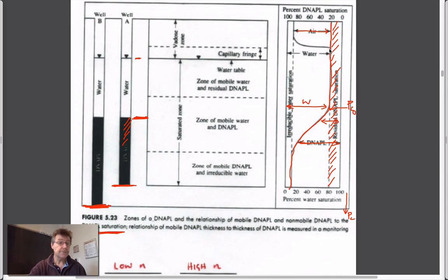And so in this case we don't have to worry as we did before, but I guess the other thing which is important to notice, say the capillary barrier was here, and you drill a hole down to here. Well, of course it will fill up to here based on what falls out of the aquifer. If you now over-drill this hole, so now it's deeper, and it still has a capillary barrier, this would still be the limit to which the DNAPL had penetrated. But the mere fact that you have a borehole that goes down deeper is that the bucket will just fill up with more water, or more NAPL, because it can come out of the stuff that's already there.